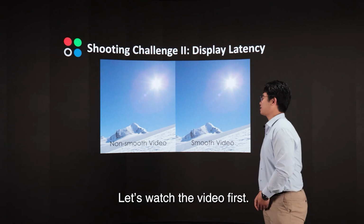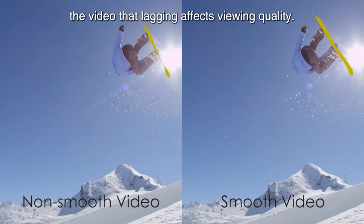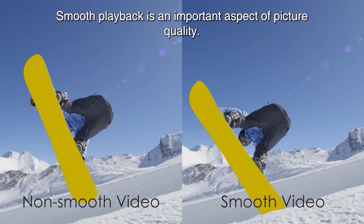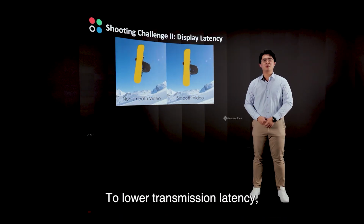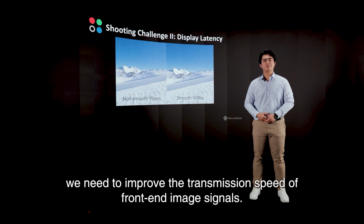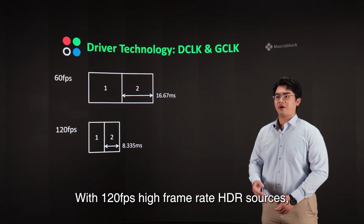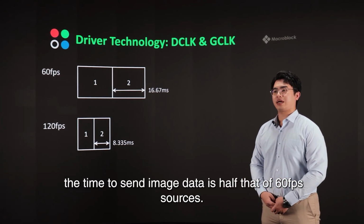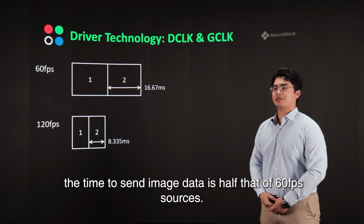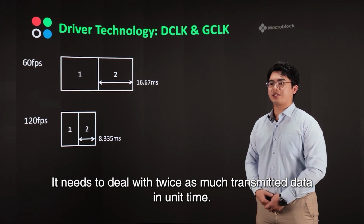Let's watch the video first. We can see how video lagging affects view quality. Smooth playback is an important aspect of picture quality. To lower transmission latency, we need to improve the transmission speed of the front-end image signal. The LED display also needs to support low latency transmission. With a 120 FPS high frame rate HDR source, the time to send image data is half that of a 60 FPS source. It needs to deal with twice as much transmitted data in unit time.